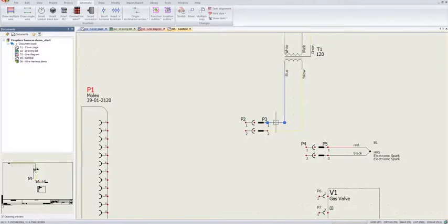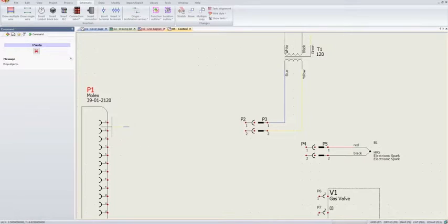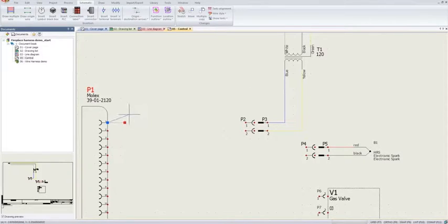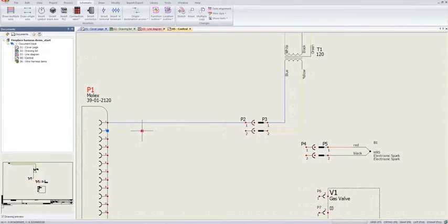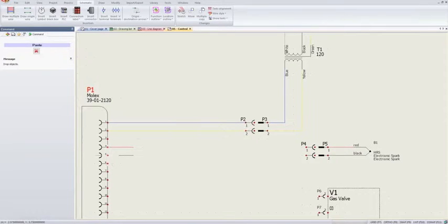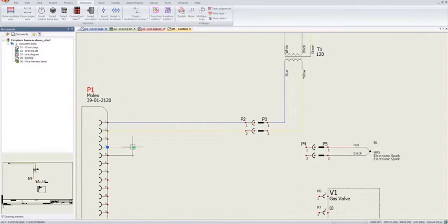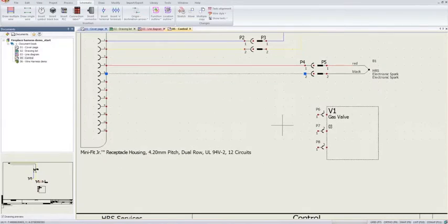Now one of the ways that we can do this, there's numerous ways. You can do a copy and paste. And the advantage of a copy and paste is that I know it's going to be the same exact line wire style. Right? So for example, the same one here when I'm doing my yellow, say if you're inheriting this project from somebody else, right? And maybe you don't know exactly which one that is, you can do a copy and paste. You can do multiple, for example, this red and black, and then paste those in there. I'm just doing a control copy and paste, control C and control V to paste it. But of course, if you're the one that knows exactly how this is going to be connected or the wires aren't there yet, right?